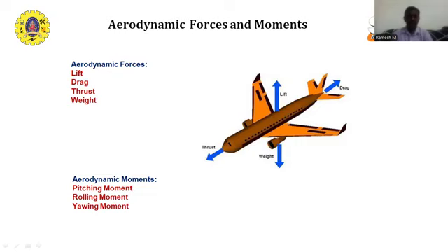For jet engines, it is often confusing to remember that the aircraft thrust is a reaction to the hot gas rushing out of the nozzle. That means in the nozzle, the flow of air or any gas will be faster at the outlet. That is the function of the nozzle, to increase the velocity. Here, the hot gas goes out the back, but the thrust pushes towards the front.